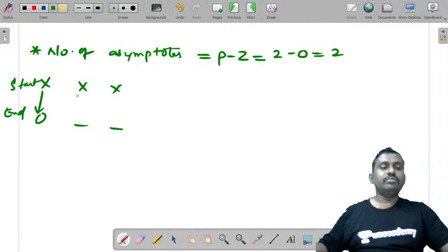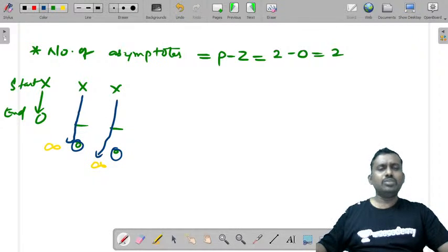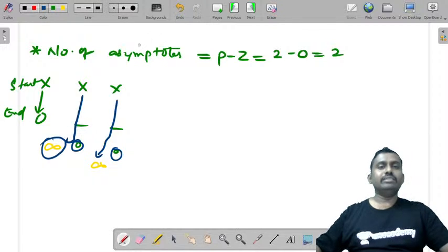So these two will end at some point; there should be some zero somewhere. We assume that the zeros are at infinity, and these poles are tending to these zeros at infinity. If we have zeros exactly in the s plane, the location is known, and we can directly find the path between them. But because they are at infinity, we need some asymptote. Asymptotes are the straight lines in the root locus which guide the root locus path to tend to infinity.